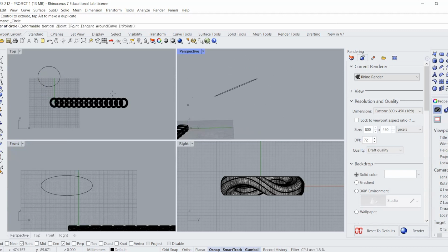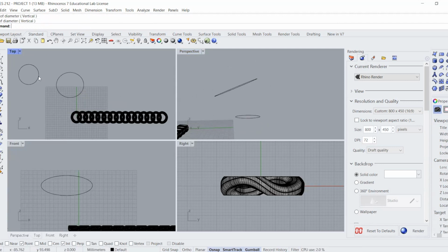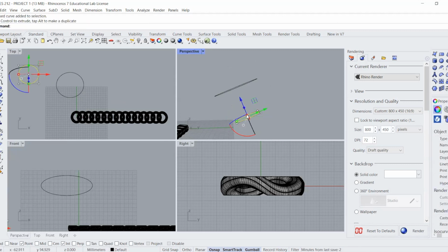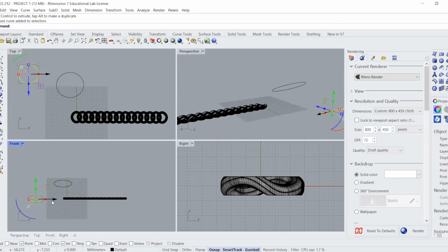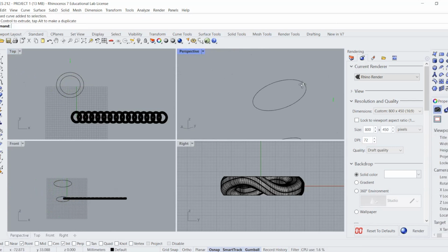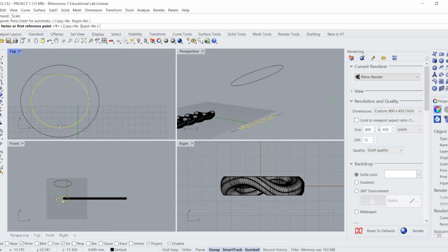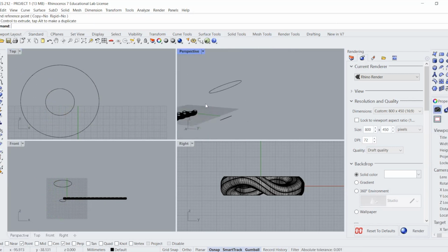So moving on, I used here a control point curve that I twisted. Rather than having a flat round tunnel, I wanted it to be at an angle. After the control point curve, I added a little line at the bottom that kind of went outwards, so that when I do the two rail sweep, it wouldn't look like a straight line. I wanted it to have a curve that went inside in the middle and then outwards to the top.